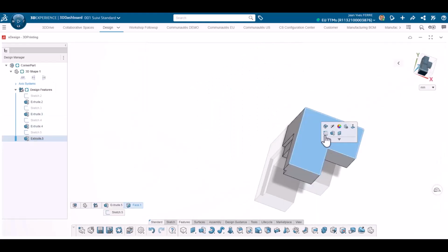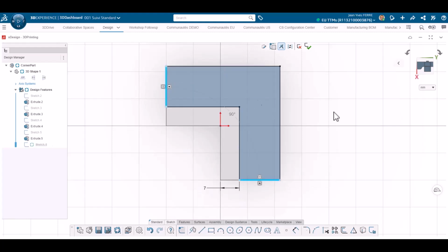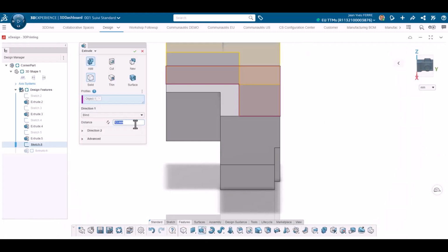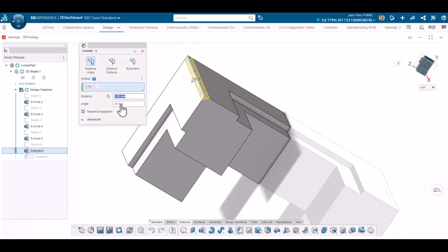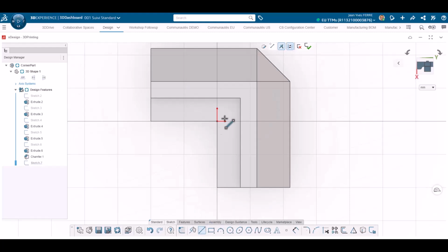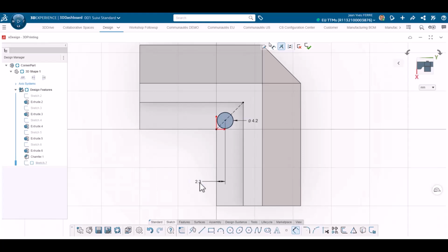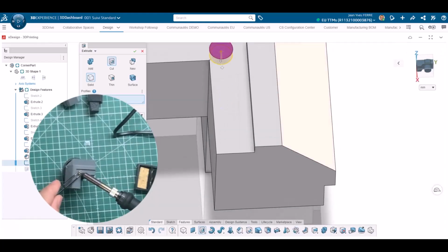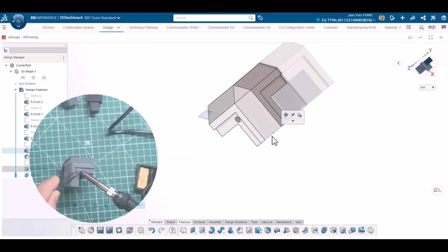I finish the recess design with the last face, and I make sure I choose the right starting plane for each sketch. Then I add some chamfers for style. It will look far better like that and will remove some sharp edges. To open easily my box, I will put some embedment nuts, and for that I need these holes. Nuts will be inserted with a soldering iron to stay in place, and of course I need this hole in all recess. That's where mirror feature kicks in.